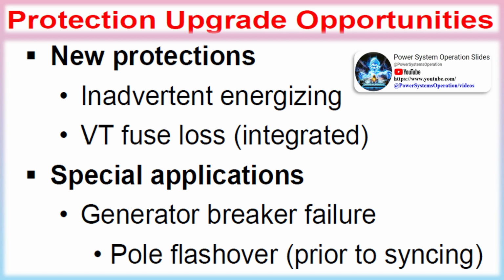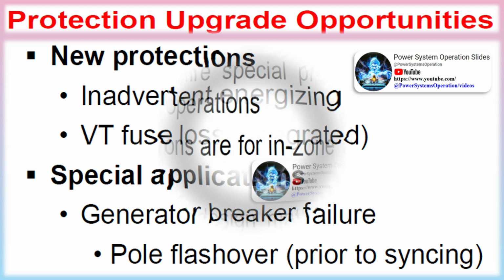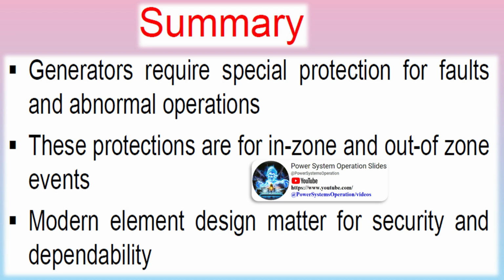Existing generator protection may not be self-diagnostic, lack comprehensive monitoring and communications capabilities, not provide valuable event information that can lead to rapid restoration. Part of NERC report comments on the August 3 blackout, not be in compliance with latest ANSI IEEE standards. Asset reliability, insurance, liability issues, see C37.102, Guide for the Protection of Synchronous Generators.